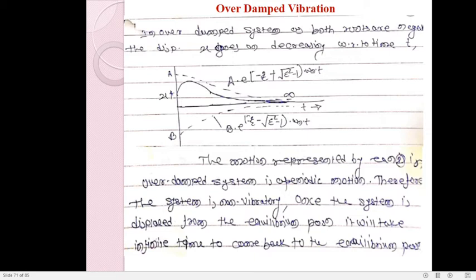But if that door closer is old and has become somewhat harder, then pushing requires much more force, and as you push, the door will open, but it will never come back to the mean position in a short time. It will take much more time to come back to the mean position. This is the example of an overdamped system.